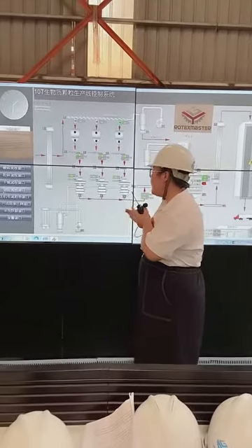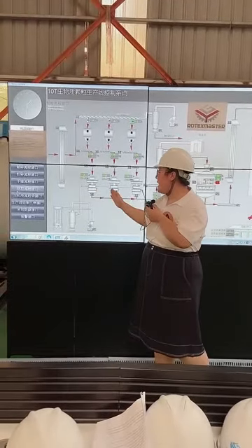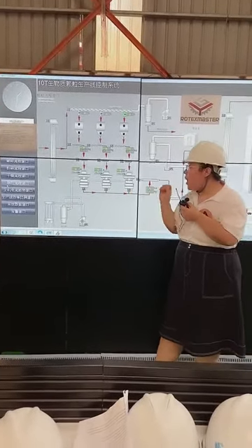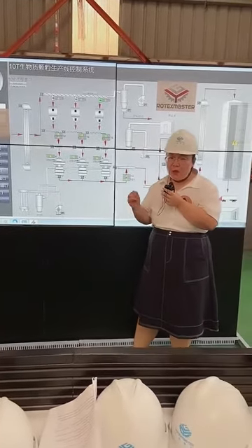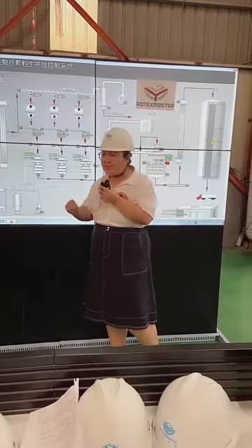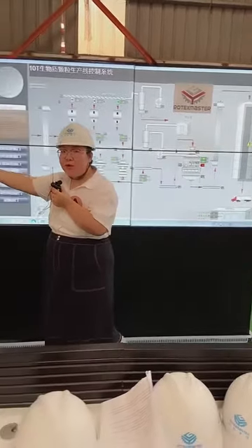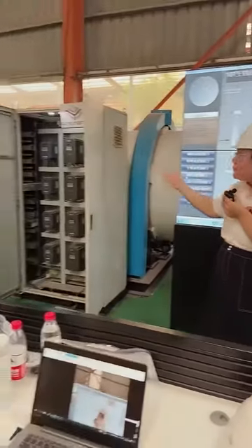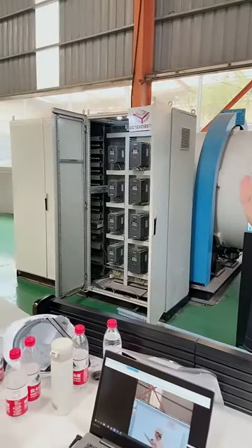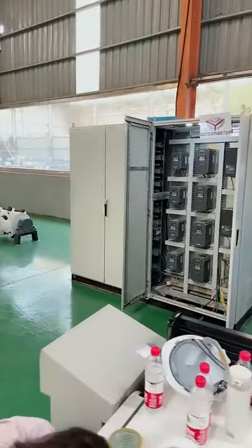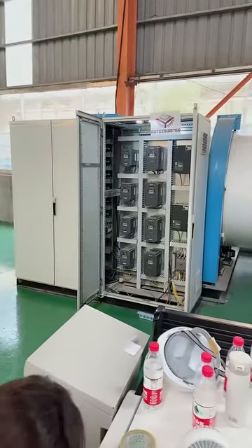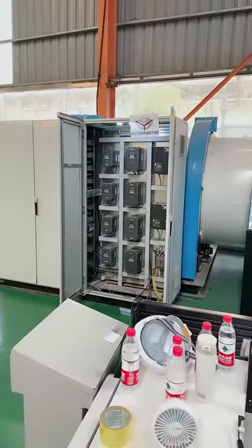For the pellet machine, its motor is large, so to protect the motor and reduce starting current, we add a frequency start in the control cabinet. It will reduce the machine starting current to protect the motor. It's very useful. When you are using a large motor pellet machine, we advise to add it.